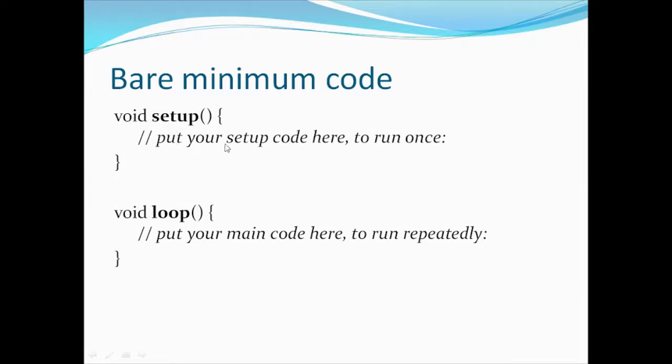Void setup in the sense you can put your setup code here to run once. It runs only once. Void loop, what it does is it runs automatically again and again and again. So for the initialization part you can keep it inside void setup, while for the looping part you can keep it under void loop.